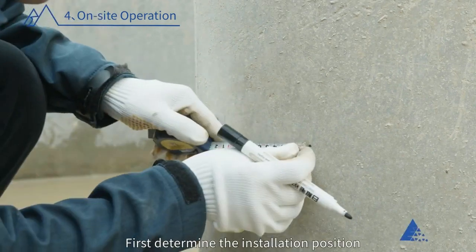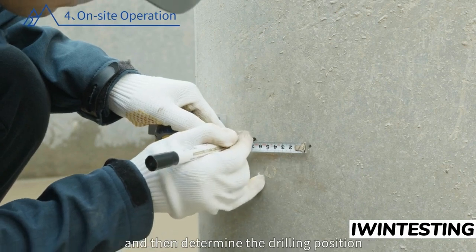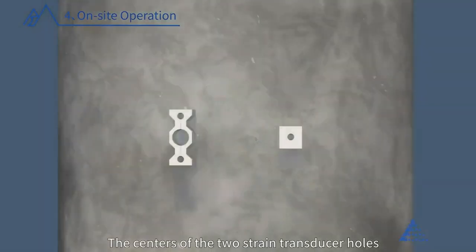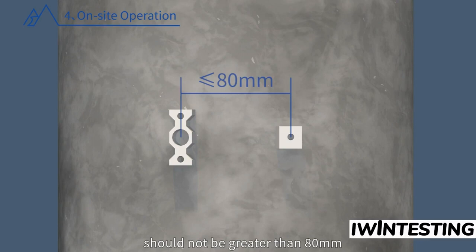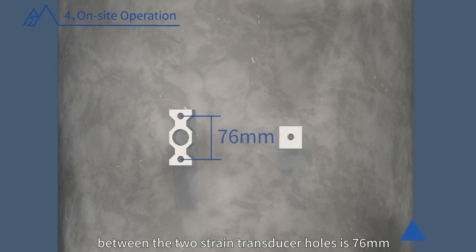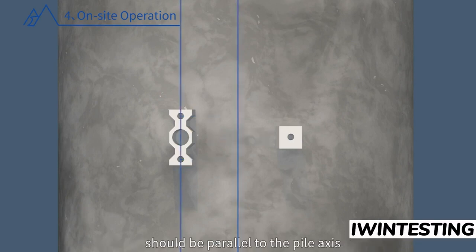First, determine the installation position and the drilling position of the accelerometer, and then determine the drilling position of the strain transducer. The centers of the two strain transducer holes should be on the same horizontal as the accelerometer holes, and the distance between them should not be greater than 80 millimeters. The distance between the two strain transducer holes is 76 millimeters, and the line connecting the two holes should be parallel to the pile axis.